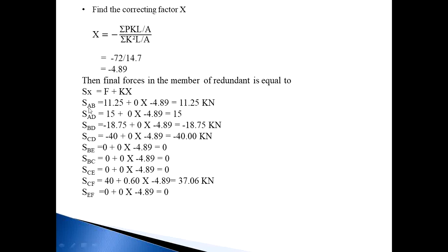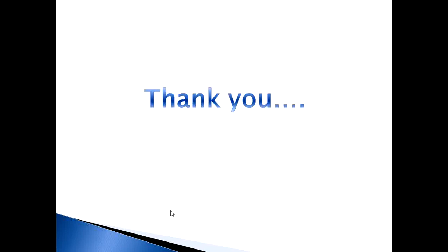In a similar manner we calculate all forces in the members, that is final forces, and SAD is equal to 15 plus 0 into 4.89, that is 15. So calculate all forces in such a manner. This is the procedure to solve an indeterminate structure by the energy method or unit load method. Thank you.